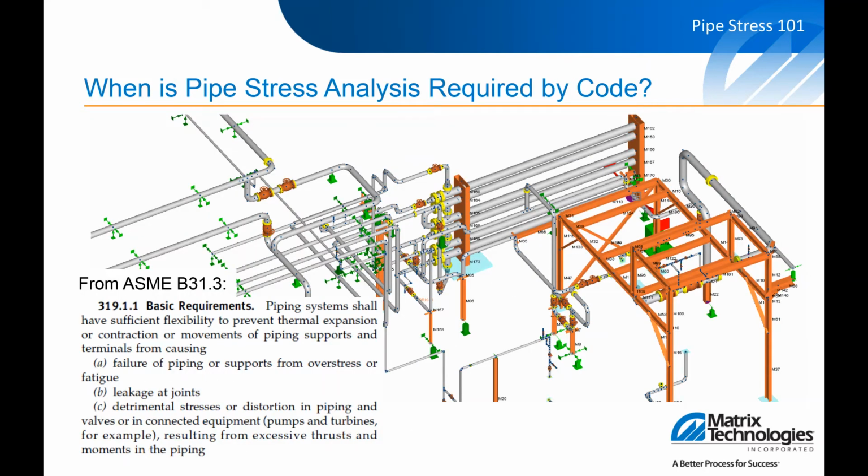Now, if you look at the code, it is a little vague. It says, piping systems shall have sufficient flexibility to prevent thermal expansion and contraction or movements of piping supports and terminals from causing failure of pipe, leakage of joints, or detrimental stresses in piping or connected equipment. So back to that very first sheet, you don't want bent pipes, you don't want broken supports, you don't want leaking flanges, and you don't want damaged equipment. So that's basically what 313 is saying.